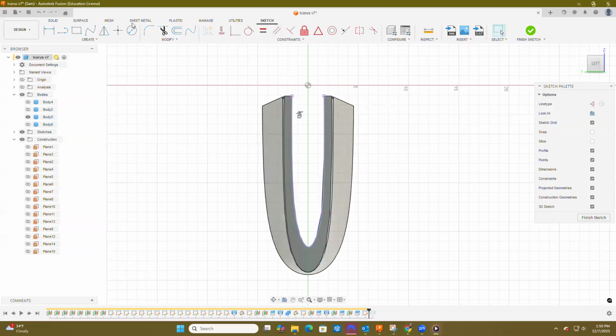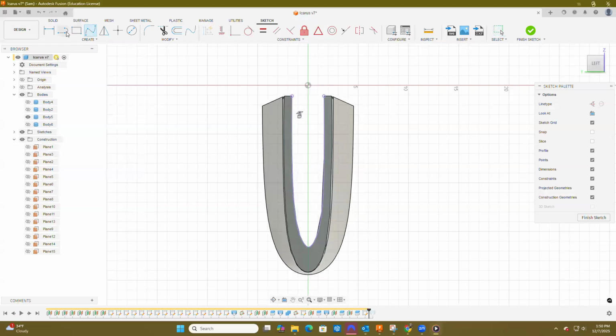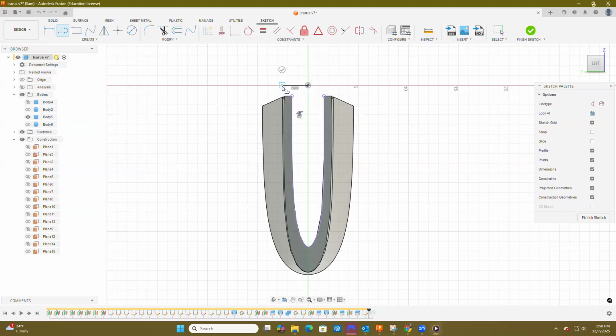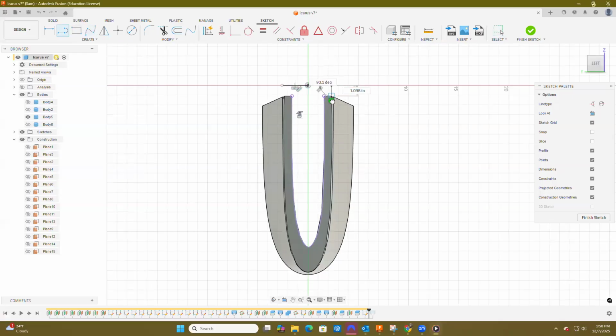All right, so now we have our shape of our canoe that's going to be on the inside of our cross section. And now we are going to want to reference it to the ground. Okay, so the ground's going to be at 0. That's how this canoe was made. With basically the bow sits at 0. The top of the bow sits at 0 for its origin. So we want to reference it to that since our cross sections will be at various heights along the whole canoe. So we have our 0 line there.